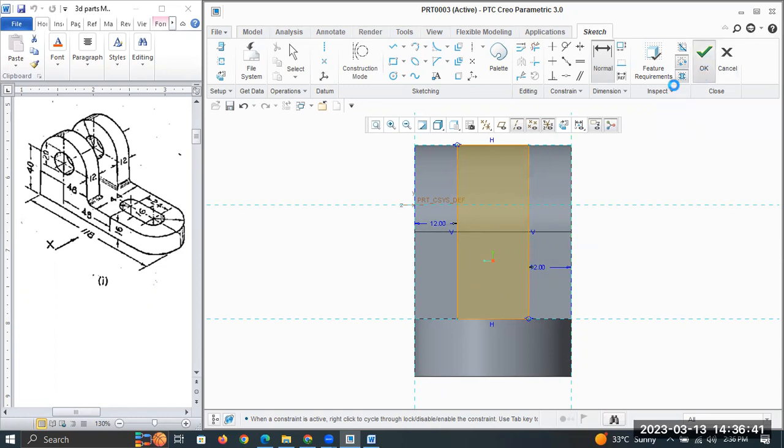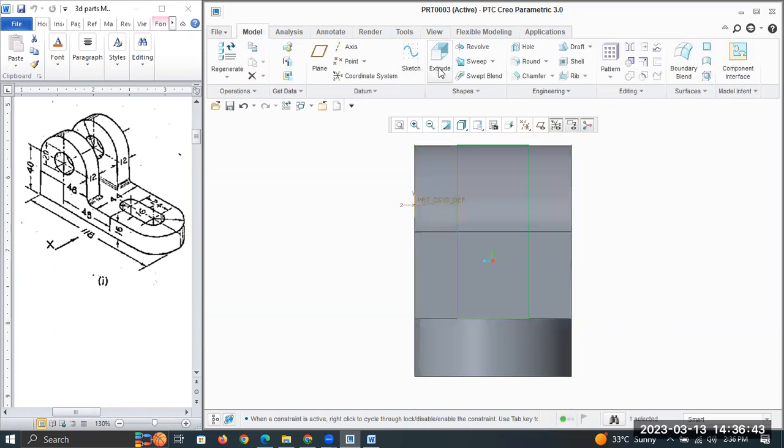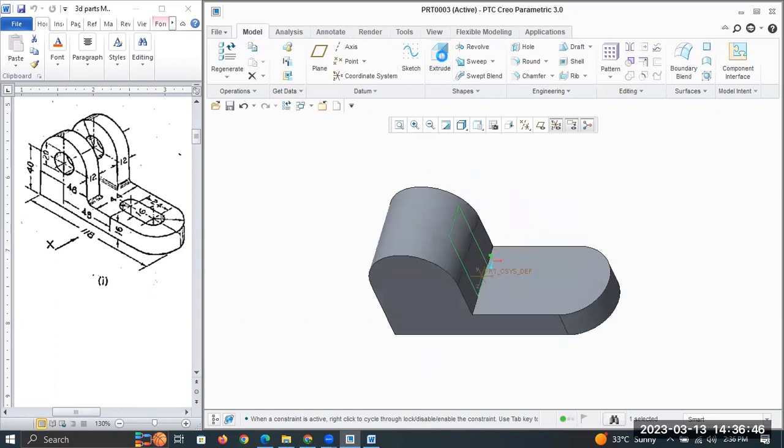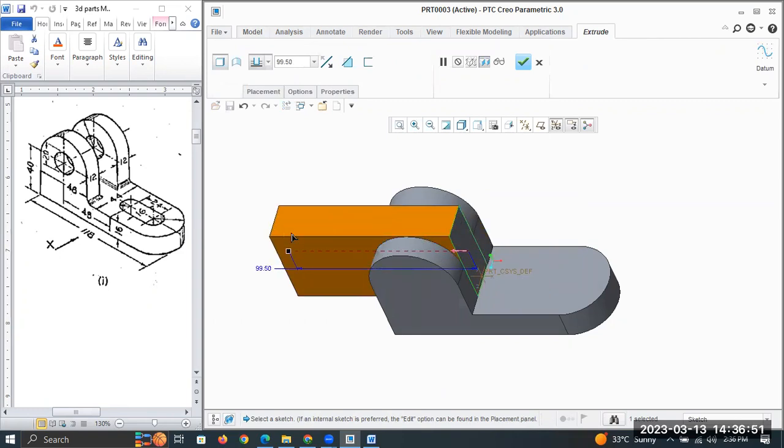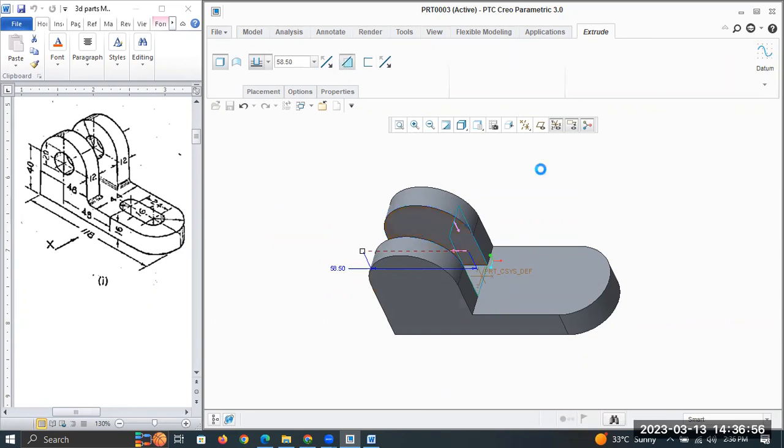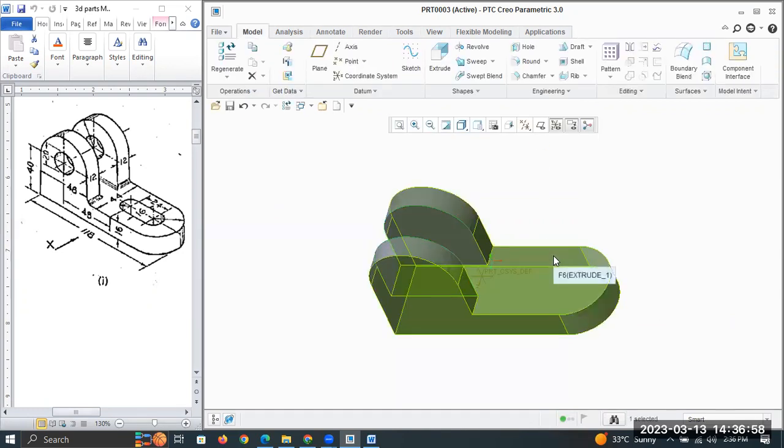Okay. So say okay. Just press Control D. Apply extrude. Just alter the direction. Please remove the material. Drag it beyond. Cut the material. Say okay. Is that clear? Right. Now see, first, whatever the material which is needed, that is going to be generated. Then first material generation, followed by that material removal. First removal is over. Second is this through hole we are supposed to produce.